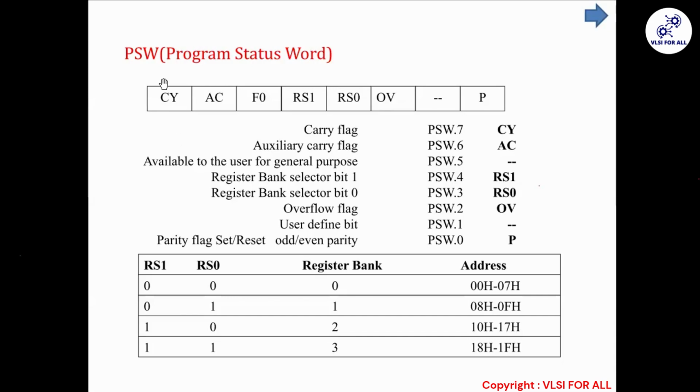So carry which is generated from the ALU will set this flag high. We will understand that carry is set there because in ALU we have chance of storing how many bits? Only 8 bits, right? That 9th carry, somewhere it has to be taken care of. So who is taking care of it? This carry bit is taking care of it. So that is carry flag.